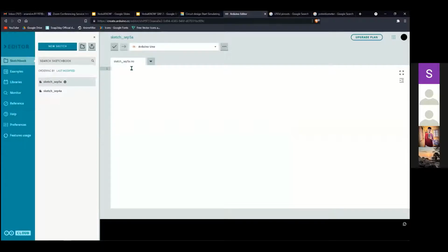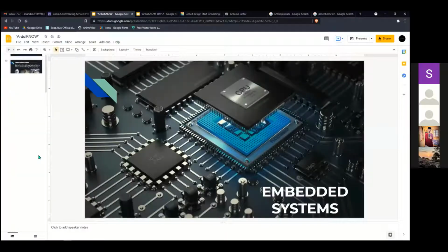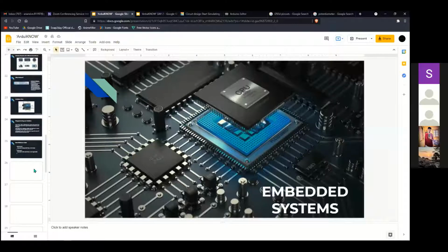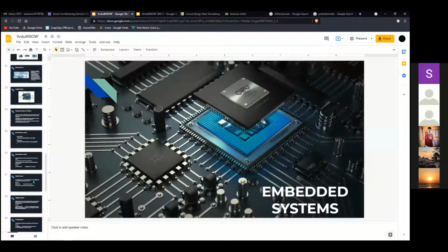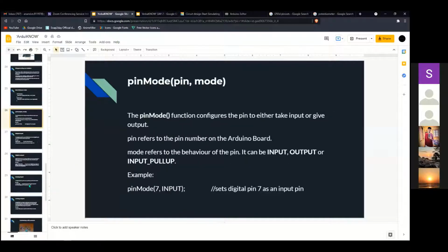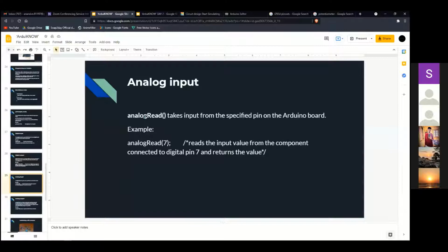In yesterday's session, we went across the basic syntax of Arduino. In order to read analog sensor values, we need something called analog input. So we'll hover onto analog input. If you see here, the basic keyword for analog input is analogRead, with braces, which defines which pin you are going to read. The same thing I am doing here.